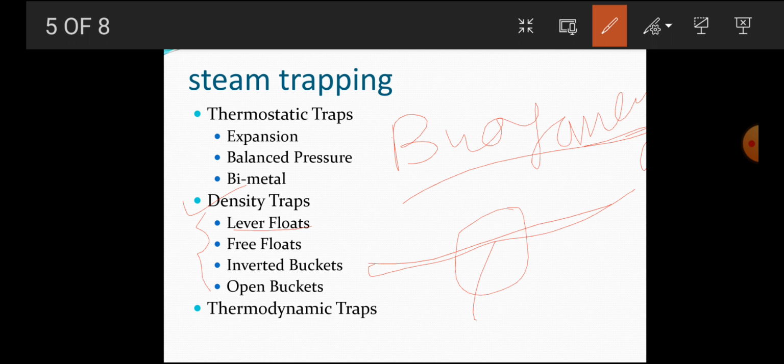So the lever arm and fulcrum point are used to open the valve, and to close the valve. They close by a combination of lever mechanism weight and net system pressure acting on the valve head.